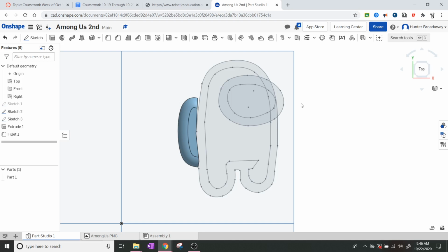For the fillet, I just used 0.2. You can play around with it and go with whatever works good for you. If it's red, make the number smaller. Make it like 0.1 for the fillet. Okay? If it's red, make the number smaller. And that hopefully will work out for you. Okay? Try to play around with the fillet and make it have the right length to it.